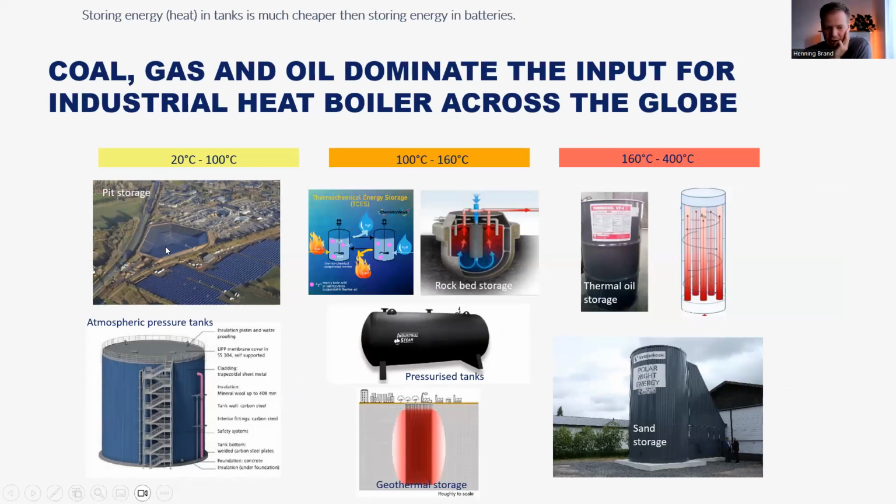Those district heating networks work with something called pit storage. They dig a really big hole in the ground, cover it with a certain lining with plastic, fill it up with water, and then put a massive lid on it. They heat this the whole summer, and this is an installation in Denmark. They heat this the whole summer long, and then they take the heat in the winter to heat the houses close by. And here you can use the same for, then there's also storage tank.